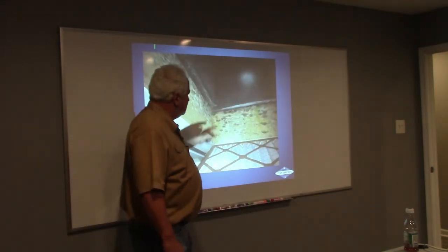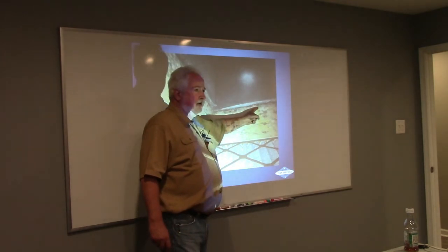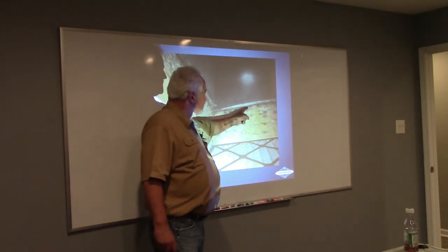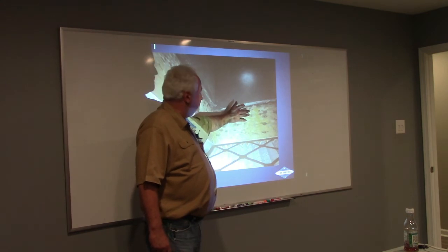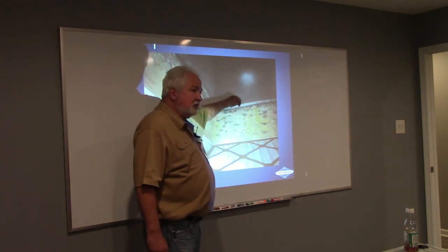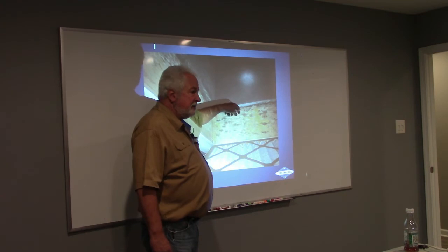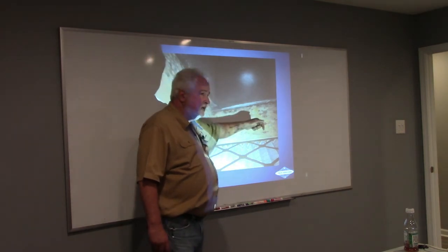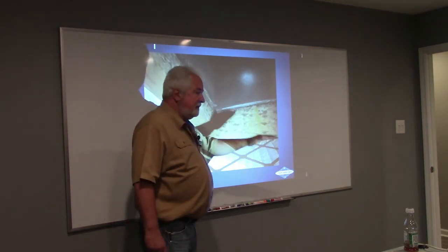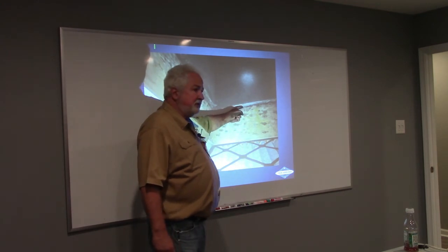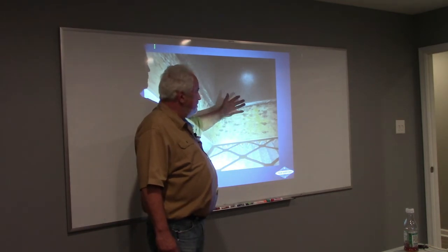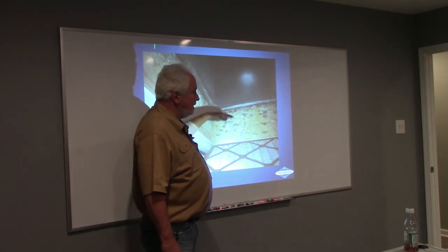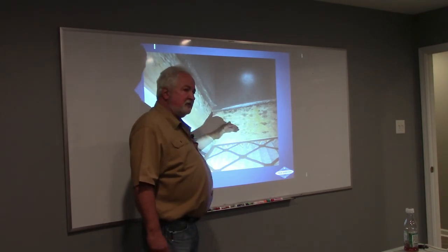What is this? Mold. Yeah, because of a return air leak. Hot and cold. I sucked in all this moisture from the attic. This was supposed to be sealed right on top of that 2x4. They were supposed to put a mechanical connection and a seal. If they didn't put the seal, dust starts pulling in here. You needed some silicone. Every time that unit turns off, that moisture comes pulling in right into this cool area.